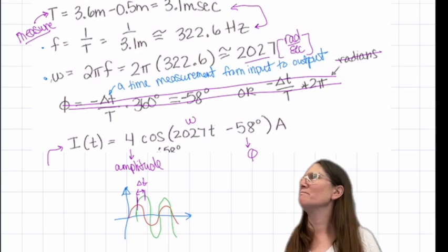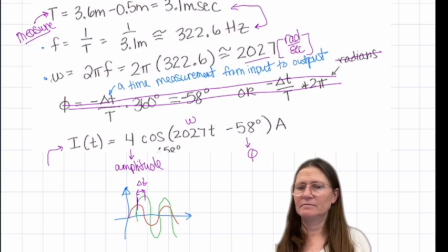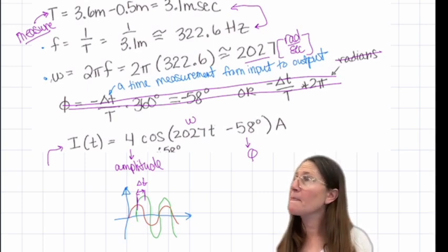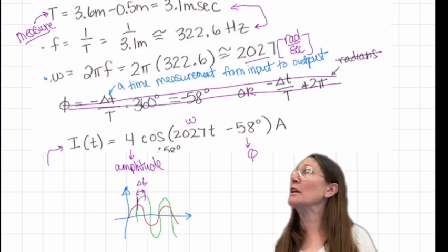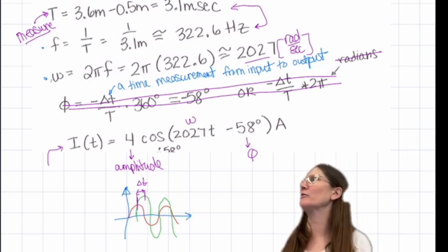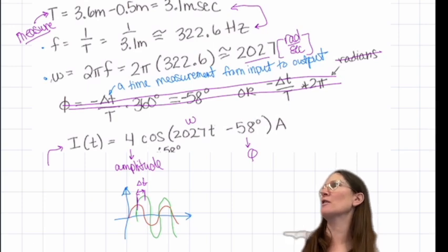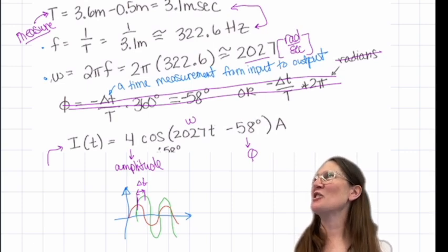Did you have a question? Yeah, so the omega t is in radians, right? Because it's in radians per second. Uh-huh. And then phi is in degrees here. Yeah. So would you normally be mixing that with radians, or would you have to convert to make sure it's radians? So usually you would put them in radians together. If you're doing it by hand, you would put them in radians, find it at a specific time, and then put that on the plot. But usually you're going to use a graphing tool to help you graph that.